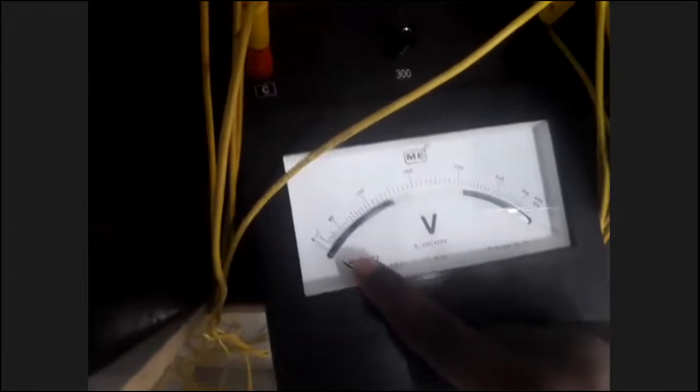Right? See, I will switch on this MCB. After that, my auto transformer is at 0 position. Then I will switch on this MCB. So for protection purpose, we are using two MCBs here. Okay, I will switch on. Now, see here. At this situation, the input voltage given to the transformer is nothing but 0, right? What is the value? 0, no?